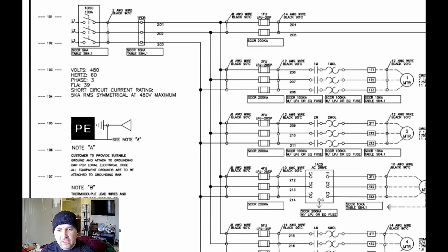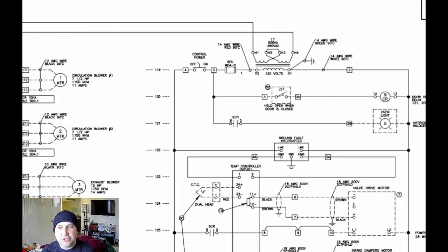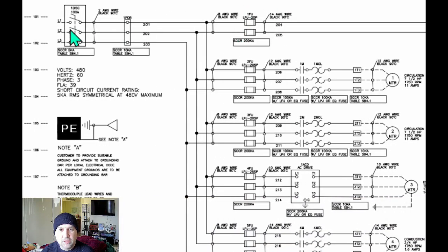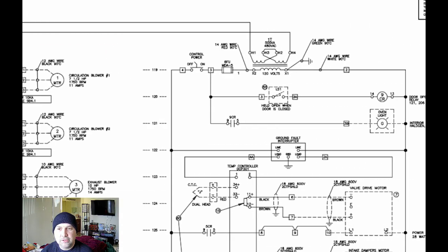Keep it pretty basic. A lot of times when they're manufacturing a panel, they just run the same circuit over and over and over depending on what's needed. So if you look at where these other 2 wires went, so now we have 3 lines of power coming in, 3 heavy lines of power go feed the motors directly, and then you have 2 lines right here off of A and B taking off that are fused right here. And what do those do? That's going to be headed over to your transformer.